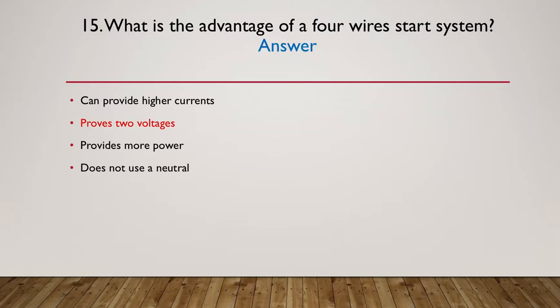The answer is provides 2 voltages. That's the very, very large advantage. Yes, it does in some sense provide more power, but the most correct answer is provides 2 voltages. Can provide higher currents? Well, it doesn't matter whether it's single phase or multi-phase, it's got nothing to do with currents in and of itself. And of course, if it's a 4-wire star system, it has a neutral, so it does not use a neutral is wrong. So the other 3 answers we can eliminate. So the answer is provides 2 voltages.